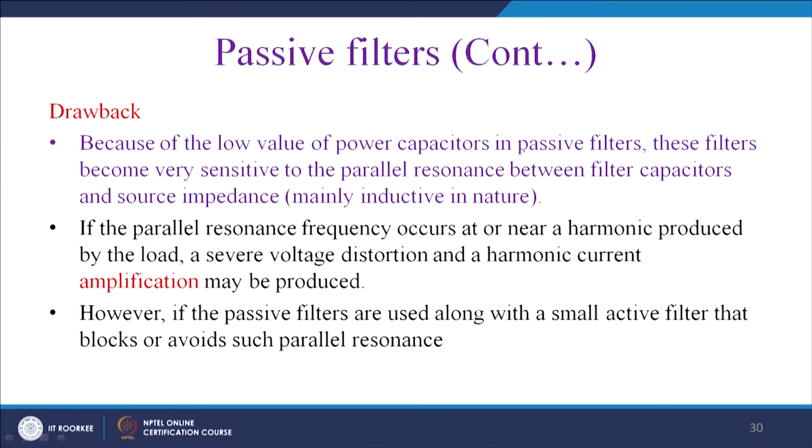Because of the low value of the power capacitors in the passive filters, these filters become very sensitive to parallel resonance between the filter capacitors and the source impedance, which is mainly inductive in nature.